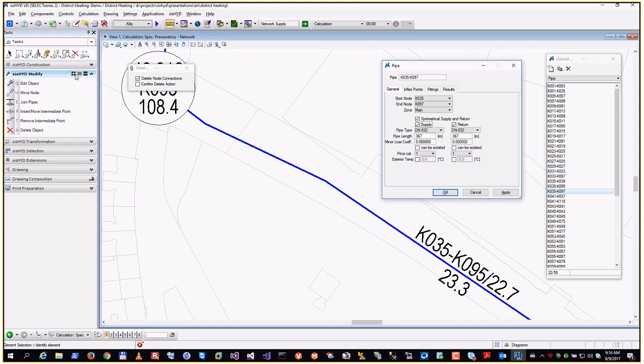We compute the pressure loss of a straight pipe, and the pipe is typically not straight. There are bends inside, and you can assign the minor loss coefficient to bends, and that accounts for this bending and that it's not a straight pipe.